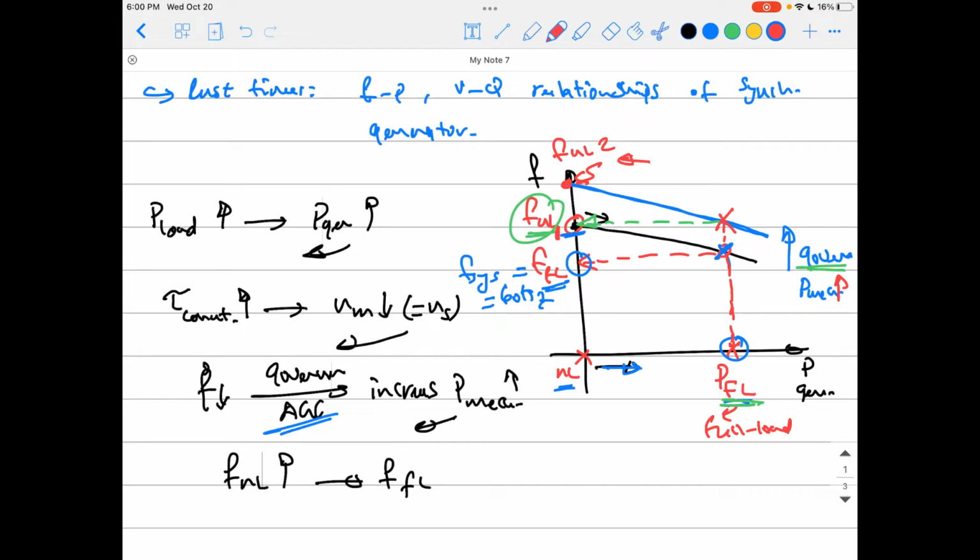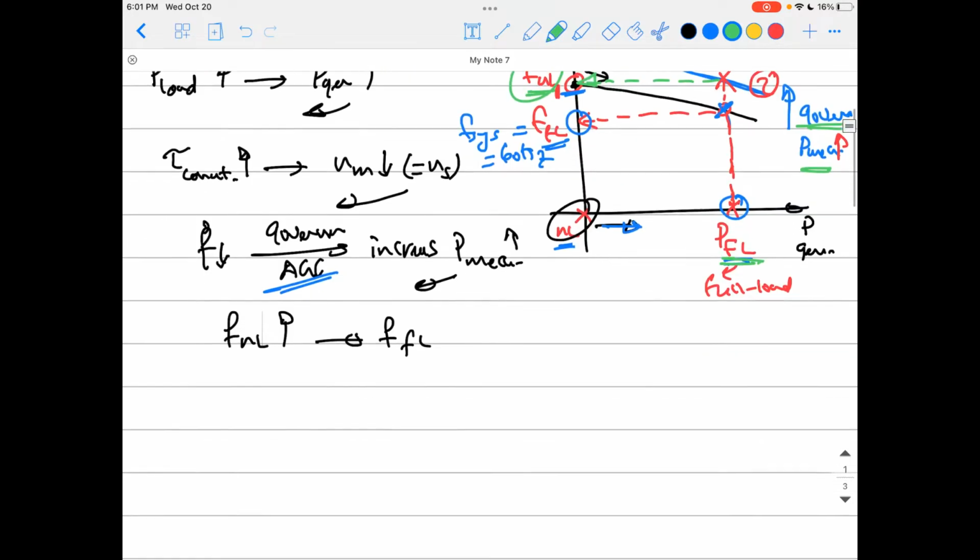So if you're now working at this increased FP relationship, call it FP relationship 2, that means if you're working at this and the power has just stopped, so you don't have any load and you're back to no load, now the frequency will be this high value. Now the no load frequency 2, F no load 2, because you're already working at a higher FP relationship by increasing the input mechanical power. And this is the action of your governor or automatic generation control.